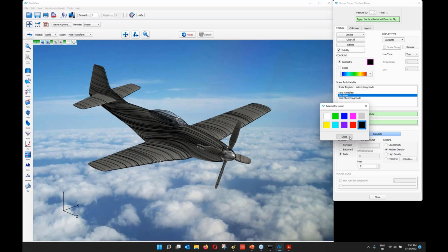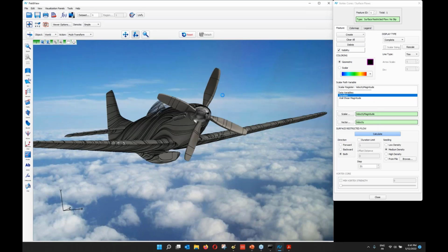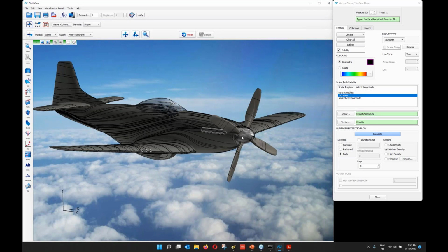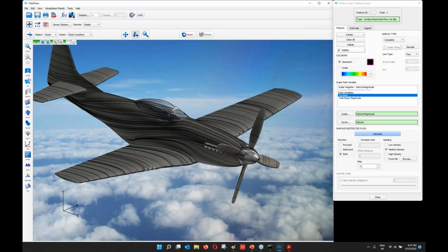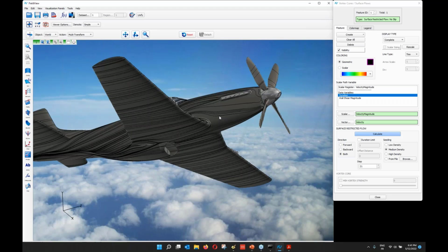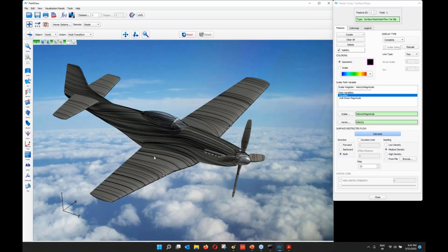And here you can see our friction line with some rotation being used by the propeller, and also you can see the different aspects of the flow. We're not running a very accurate simulation, and we don't have a high angle of attack in this case, so you're not catching separation on the wings, for instance, but that will show up with such friction lines.